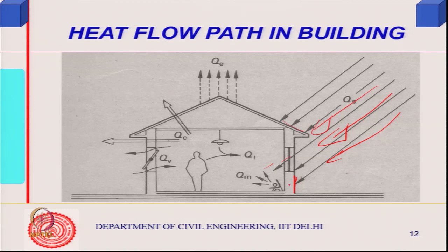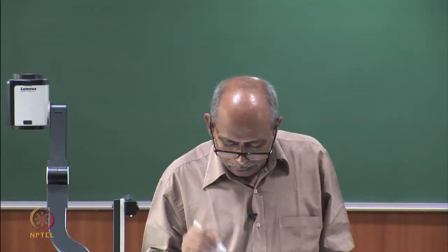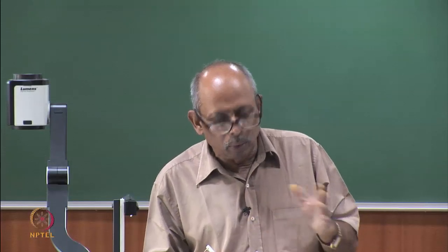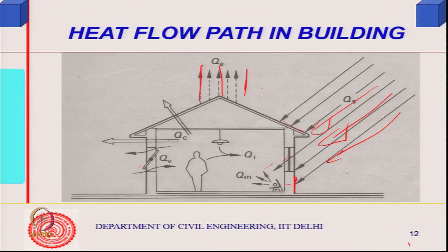this surface itself, and then it will transfer by conduction. Temperature here would result in heat conduction, which could be both ways, coming in or going out. So heat gain can occur through the wall. Some emission, radiation in the night, the surfaces can radiate back to the atmosphere. So conduction can be both coming in or going out, and through openings ventilation heat transfer can occur, which can come in or go out, whichever way.